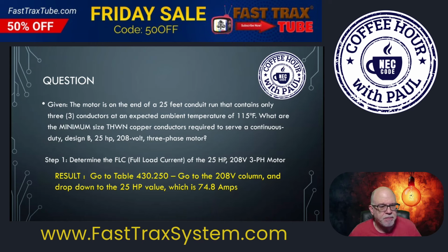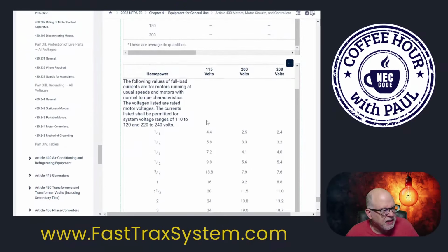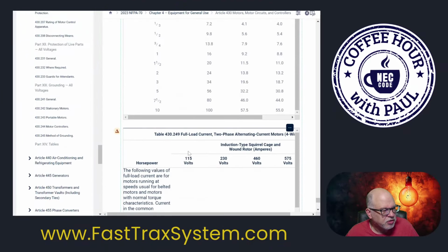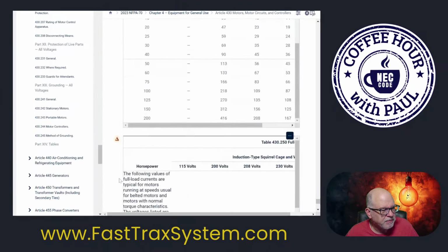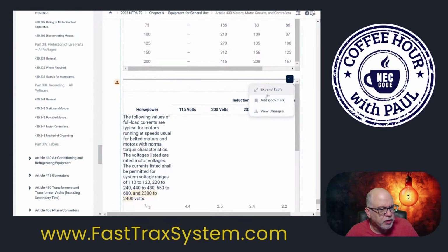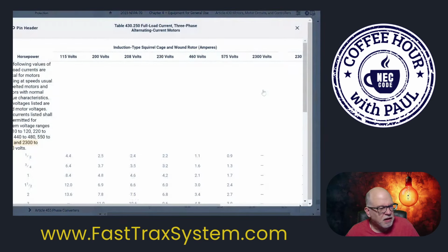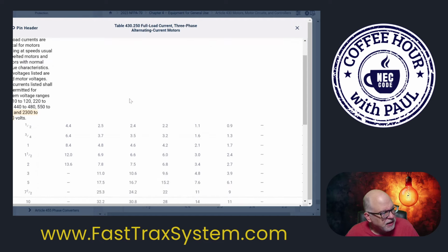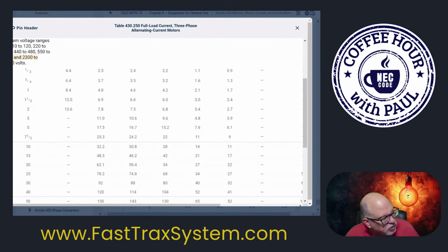Now, I'm going to say that, but we're going to go look at it. So here we are in the NEC, and we're going to drop down to table 250 right here, and I'm going to try to pop this out for you. All right, so this is what we got. So we're at 208, so this is the one we're working with, and we want to come down, and it's 25 horsepower, which is right here.